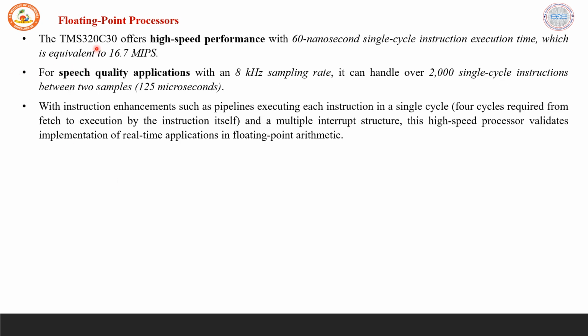The TMS320C30 offers high-speed performance with 60 nanosecond single cycle instruction execution time. This equates to 16.7 million instructions per second. To go with speech quality applications, with an 8 kHz sampling rate, it can handle over 2000 single cycle instructions between 2 samples. That is 125 microseconds.